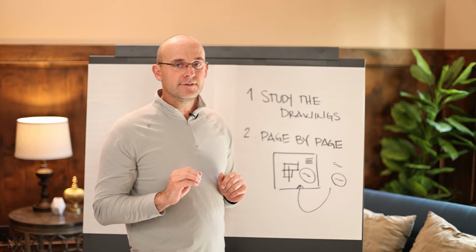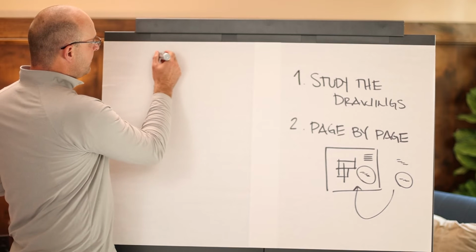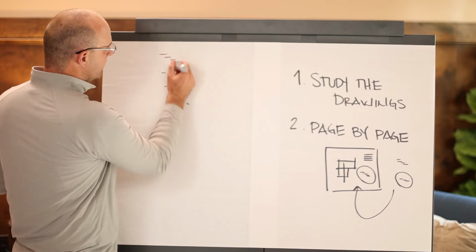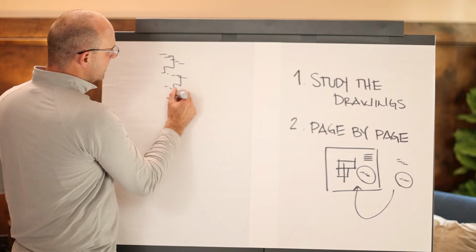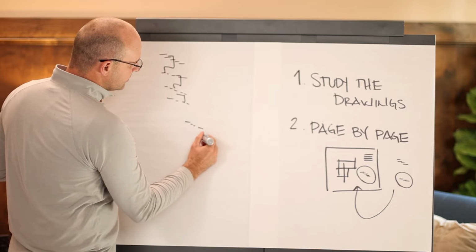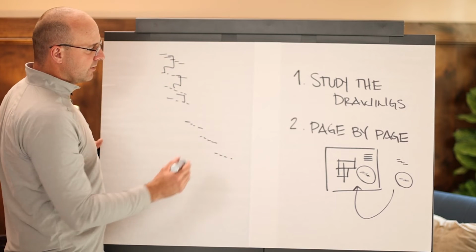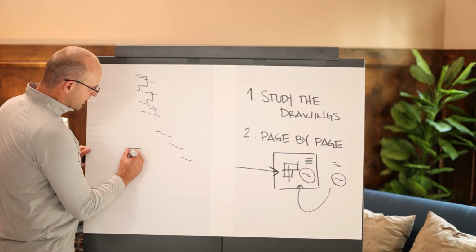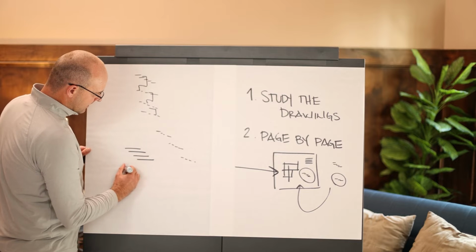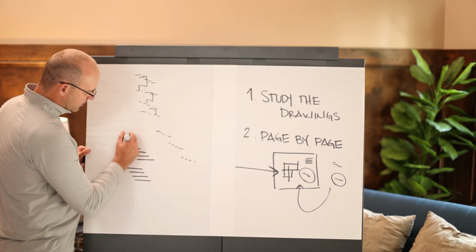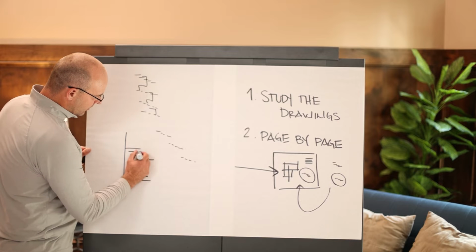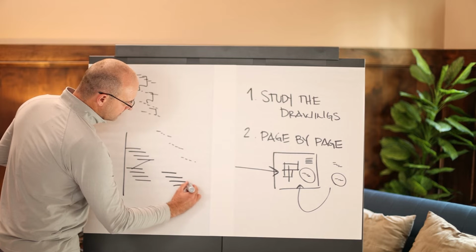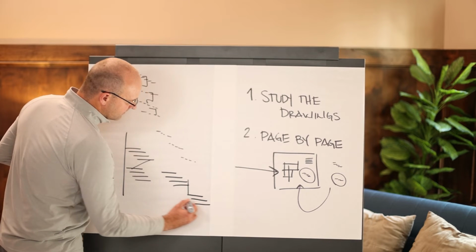Then the third part of that will be to take your independent sequences and start to logic tie them together, right? And create the right logic ties so your schedule starts to show up with the phases in the right sequence. Or these sequences that you've created in step number 2 will become tacked phases, and then instead of those tacked phases being at the same start date, you will again start to create interdependence ties to where those tacked phases start to trigger the completion of secondary phases.